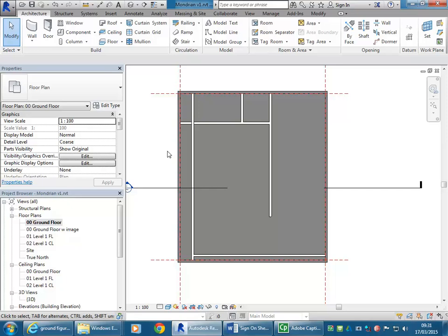So do you remember the option key you can use to get different selections in Revit? Yeah. Tab, exactly, that's right. So tab's your main option key, and if you forget these things, just have a look on the status bar and it'll remind you, and you remember that in no time. So here it tells me click to select, tab for alternates down here.